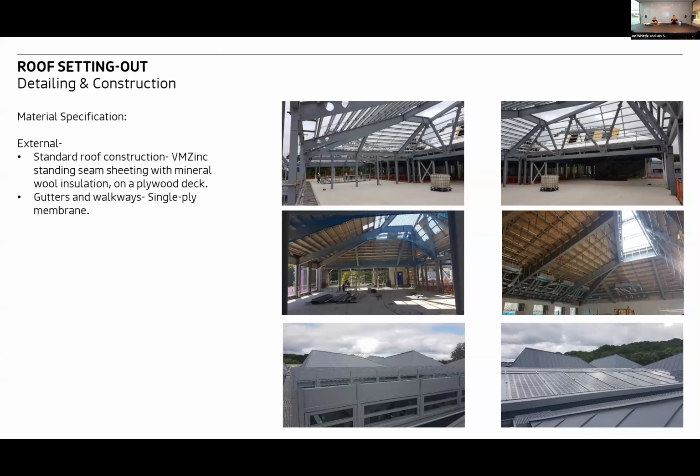This led to detailing issues because the roofs are at different angles, so they all intersect the main flat roof gutters at different heights. So there were different details in all of those locations. The gutters become wider in between the coffers, depending on which side faces which side. So it was a very complicated detailing intent, but it managed to get realised on site, which is great for us.